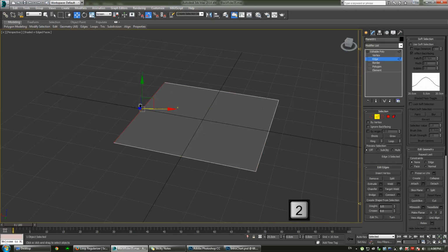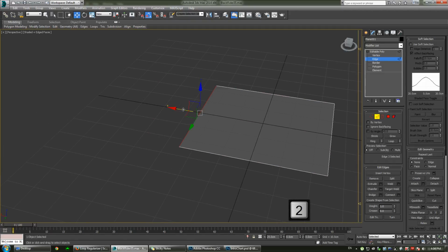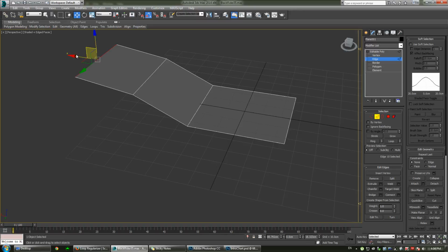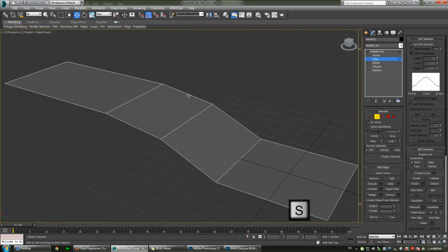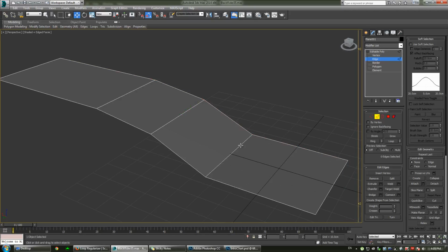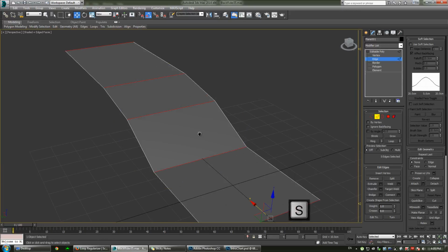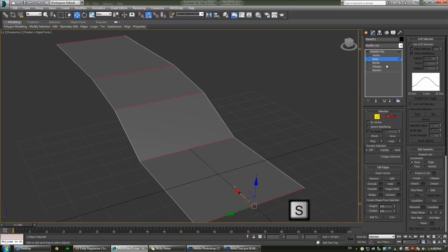So what I mean by that is I'll go here, I'm going to swap to view mode, and if I just drag out some polygons, in Max you've got a couple of nice shortcuts that will just very quickly make you select a loop. So if you double select an edge, you'll select the whole loop along that edge. And if you select an edge and then shift select the adjacent edge to it, you'll select the ring along there. And then you start having the ability to use these tools that we're seeing on the right here.